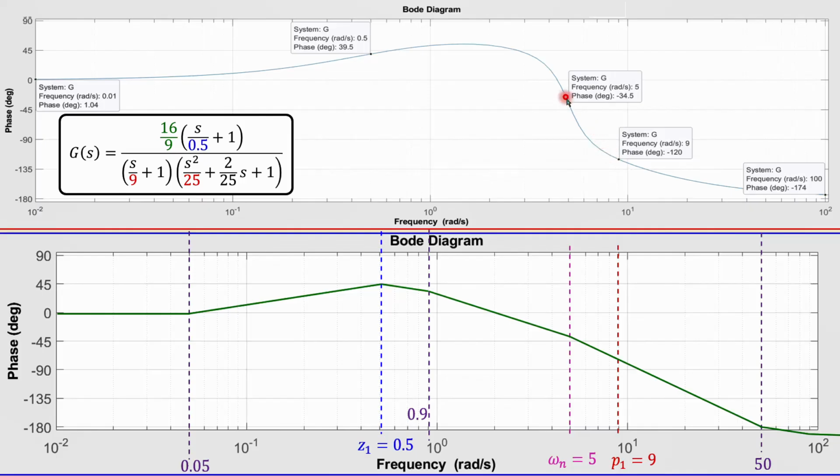But then the situation will be changed because this goes much faster, and then the slope decreases quite drastically, because this one has a slope of minus 135 degrees per decade, and this slope will then decrease not as fast as in this case. But then it will approach asymptotically the minus 180 degrees, which is not in our case. And again, if you lift this green asymptotic line up, you will get the closer value we need to have according to the actual plot. So you can see the phase plot we drew using asymptotic lines, and the phase from the Bode diagram using the simulation, the actual plot, is quite similar, using of course some correction, because you need to go up here, and then this will also go up, and then you will have more correct values.